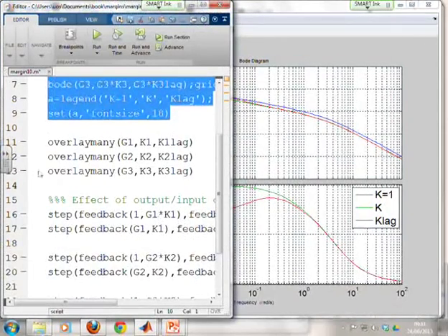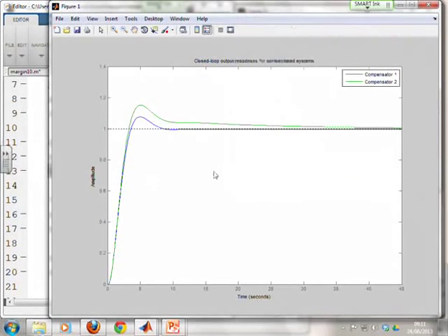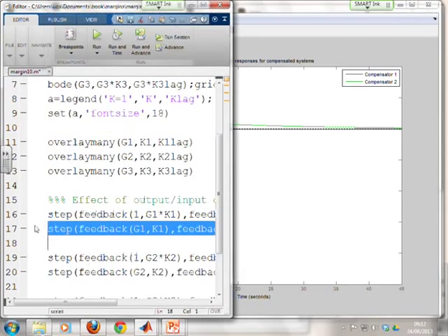If we look at the step responses, alright, so there are the output responses, and again you notice in this case, because the system included an integrator, the simple gain design seems to have a better response, because it doesn't have this really slow mode. And because you have an integrator, you don't need gain recovery to get zero offset for tracking simple steps.